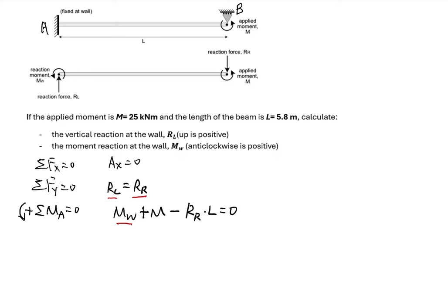First of all, we cut this beam arbitrarily at some section A to A, and build up the coordinate system x, y, where the cut is at some distance x. After cutting the beam, we can draw the beam segment over here.